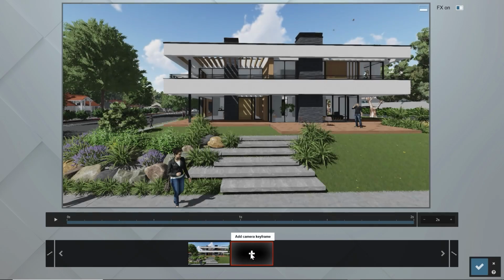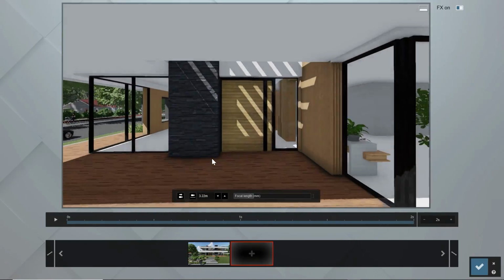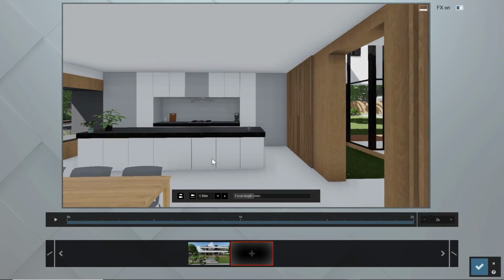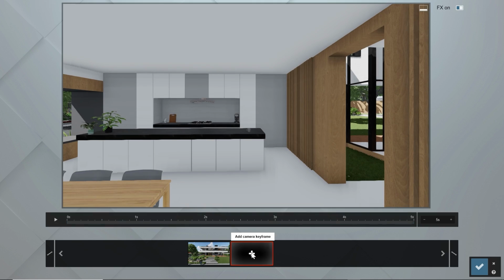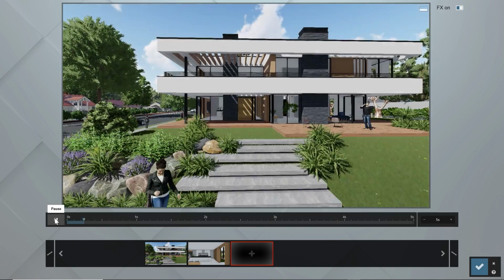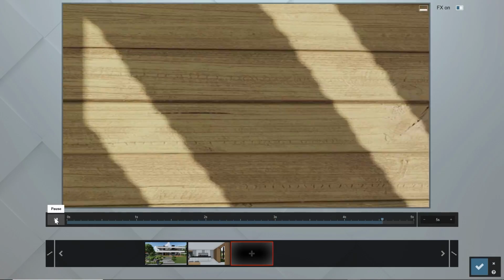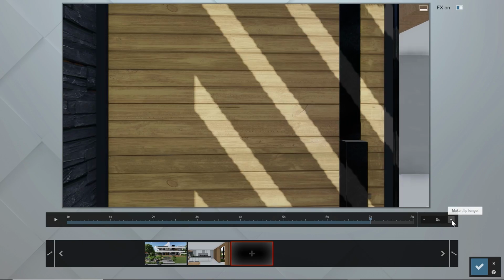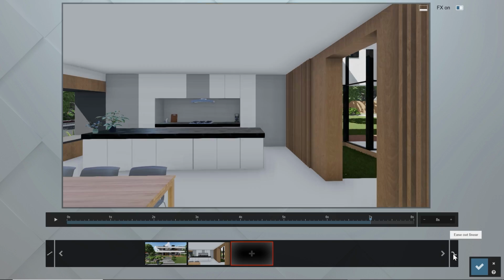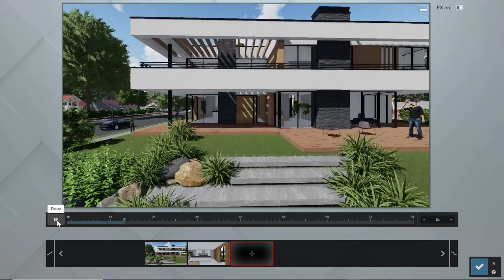Place it at its initial location in the door frame and add the door materials again. Now, let's make an animation that starts in front of the house and goes through the door and ends inside, all at an eye level height. That goes a little bit too fast. Increase the time to 8 seconds and set the ease out to smooth. That looks much better.